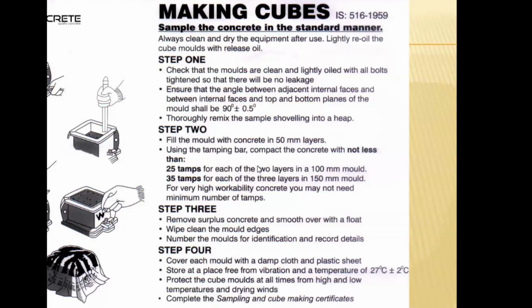Everywhere we have to follow a proper procedure, and these cubes have to be stored properly before they are moved to the curing tank. They have to be protected by polythene sheet so that evaporation does not take place. So these are some precautions we have to take. If you simply don't follow this procedure of making the cubes properly, you will get results which may put you in a quandary whether to accept the result or whether the concrete is good or bad. So we need to follow a proper procedure.